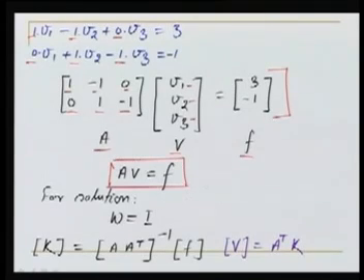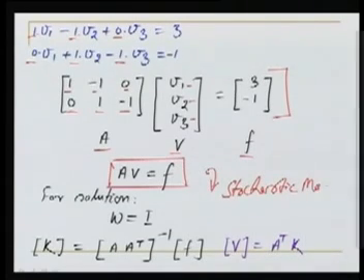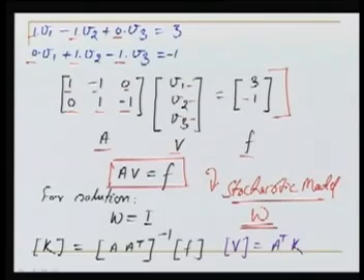Now we need to look for, at this stage, the stochastic model. Means, what is the weight matrix? If we know about the weight of these observations, we will consider those. Over here, we are considering the weights to be the same, the identity matrix. So all the weights are the same, all the observations have been taken with the same precision. So the weight matrix is identity here.